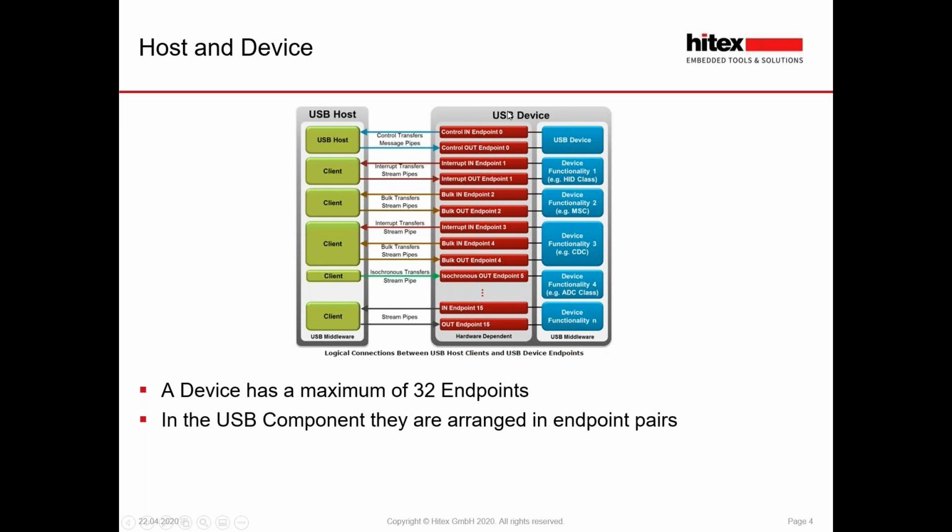When we connect a device, it always comes up as USB device 0. The host can then negotiate with it, and the device will download a set of descriptors during an initial enumeration phase, and this then tells the host what classes it supports and what endpoints it's got.